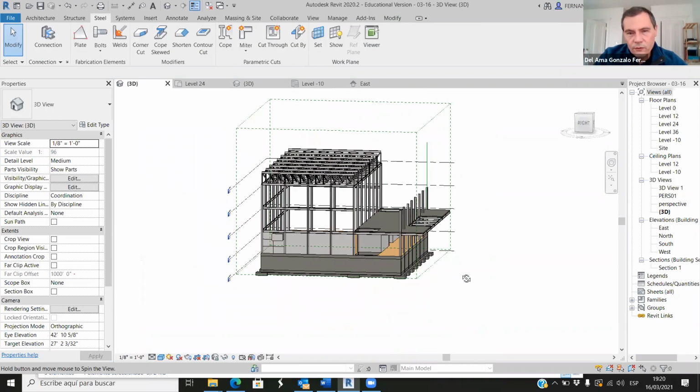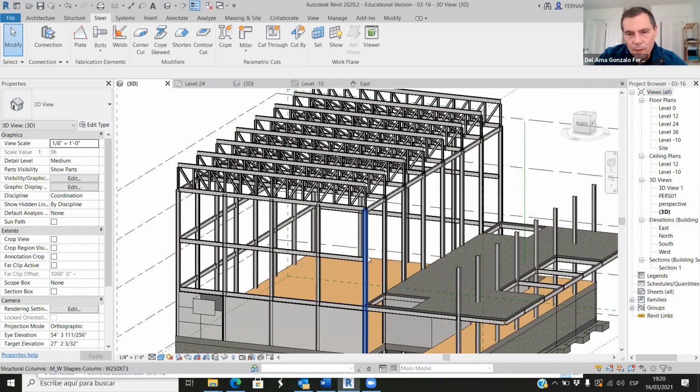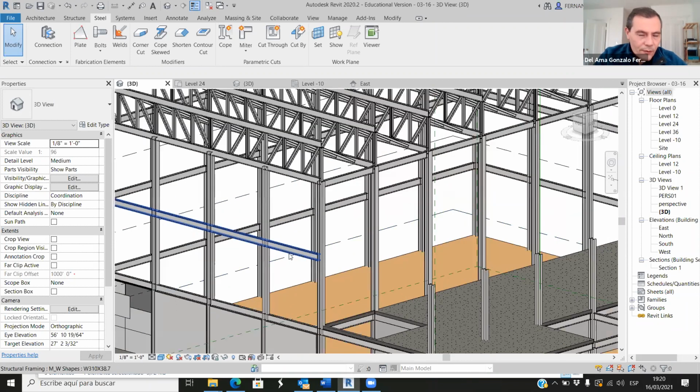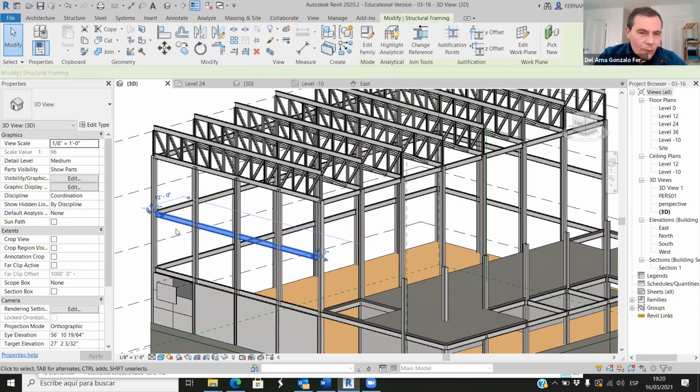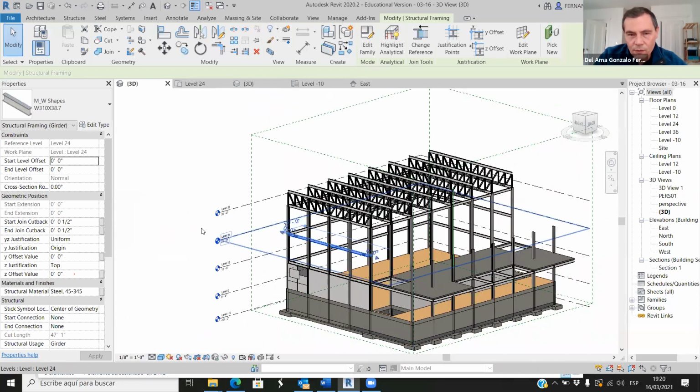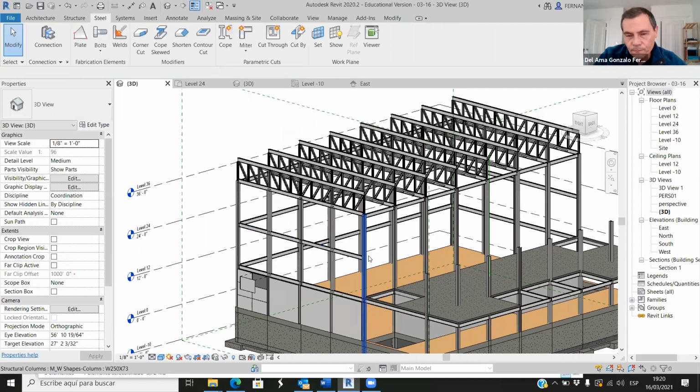And what I'm going to do now is continue this beam here, as you can see. But I want to create a profile. It's not going to be a horizontal beam like this one or this one. Oh, and another interesting thing. When I created that beam, it's a continuous beam from this point to that point, but I want this beam to be not continuous. So I will create an element here and then I'll copy.